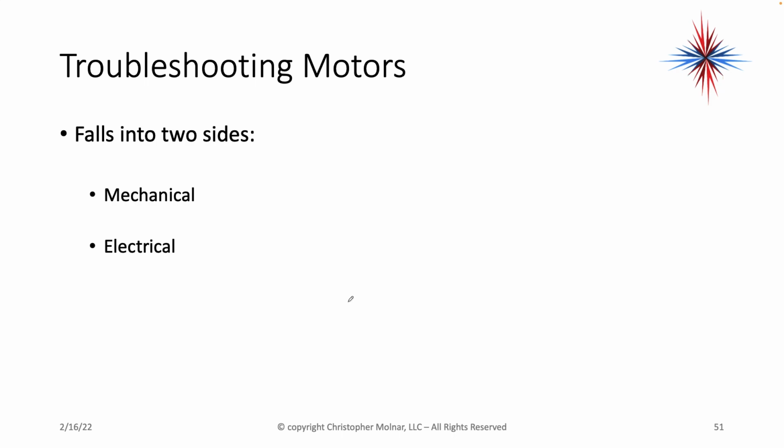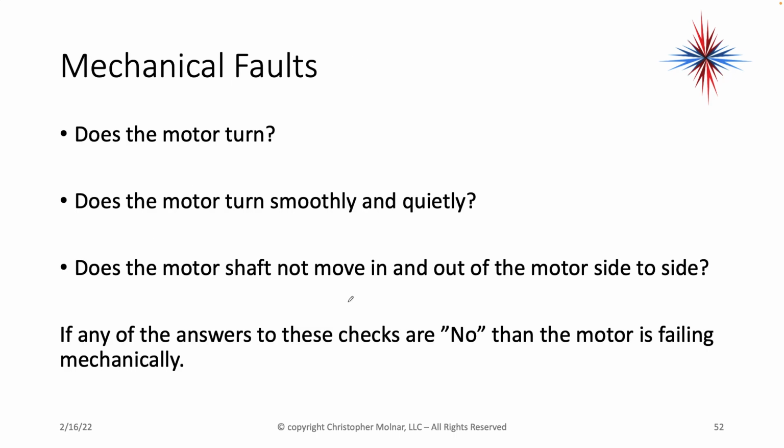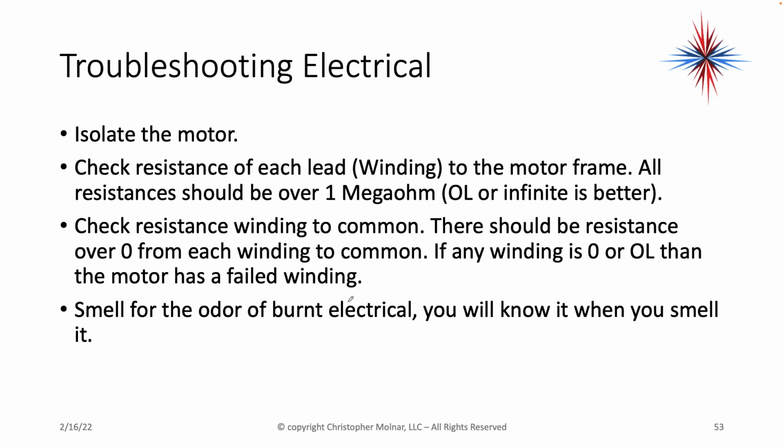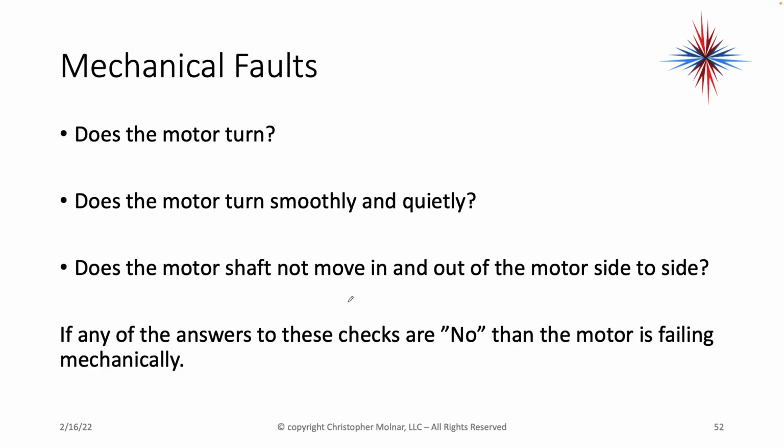Troubleshooting of motors falls into two sides, mechanical side and electrical side. Mechanical faults. Does the motor turn? Does the motor turn smoothly and quietly? Does the motor shaft not move in and out of the motor or side to side? If any of these answers are no, then the motor is failing mechanically. And by the way, does the motor turn? I mean, if you try to turn it manually, does it turn?